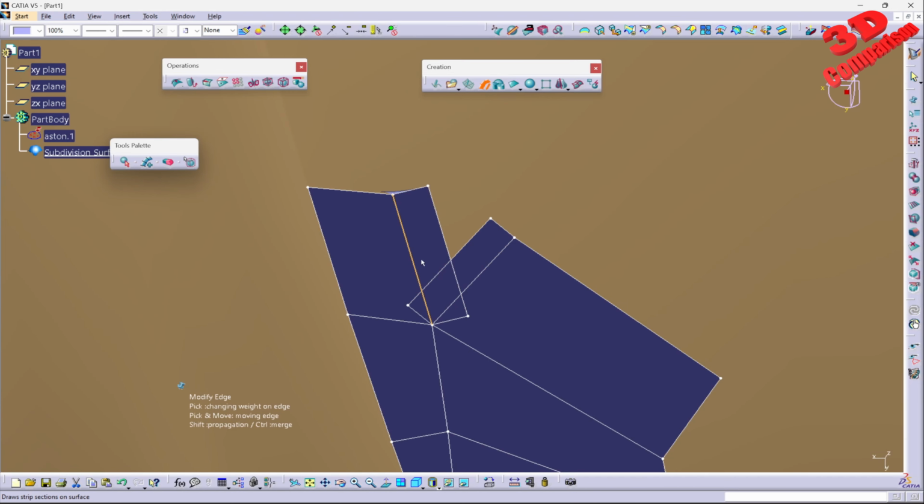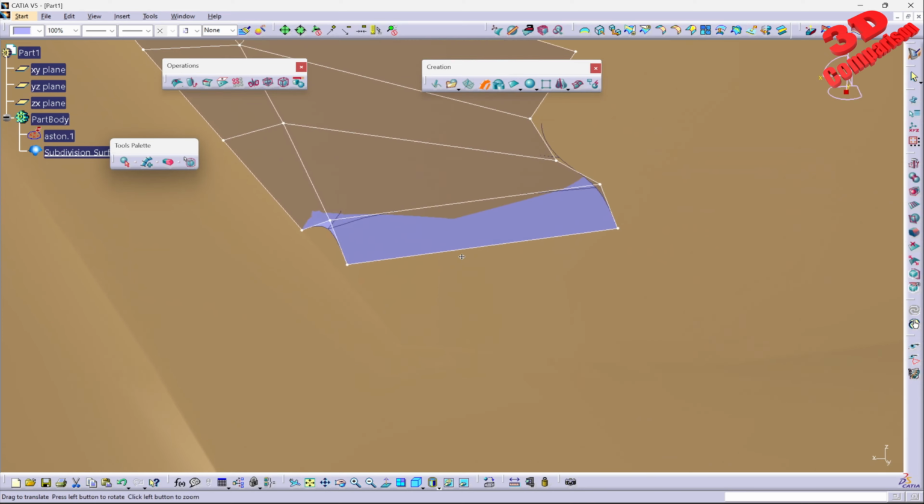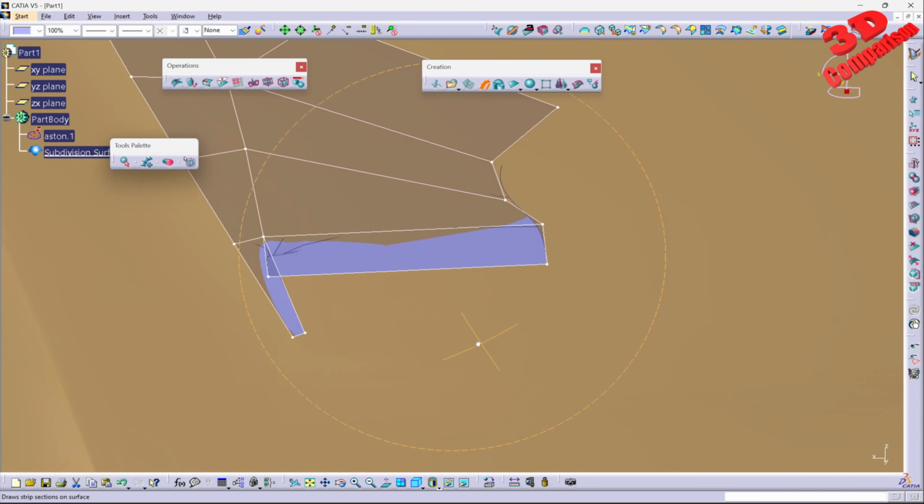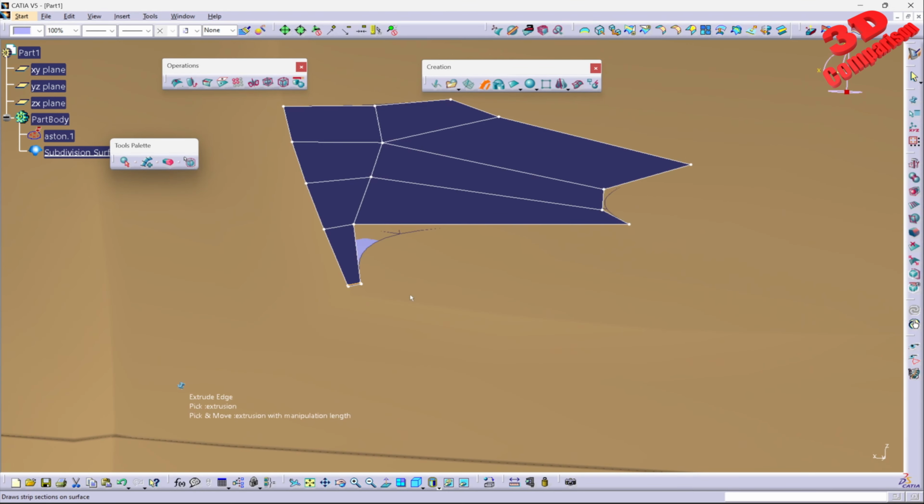And if you are having this overlapping faces, you can just select the endpoint, and if you're going to move it close to another one, you're going to see that it will automatically snap over there. And using this method, we can create additional geometry that is added over here directly. We're going to see how that will have the following output.